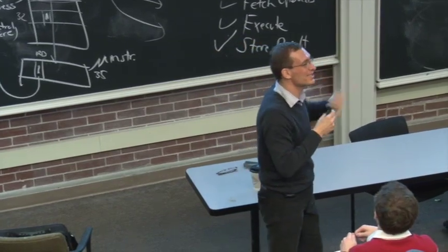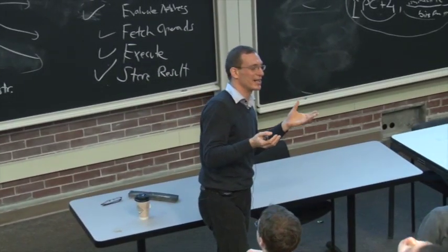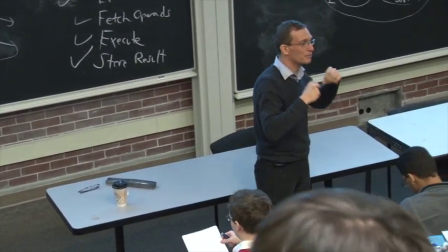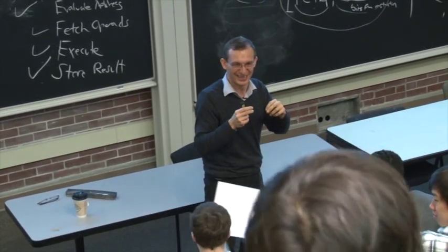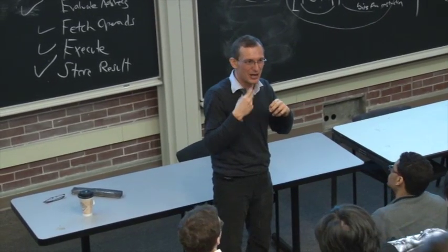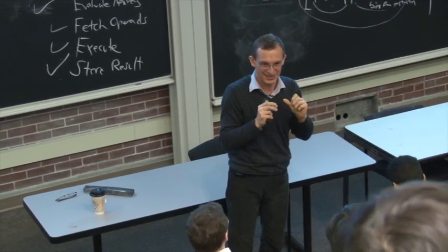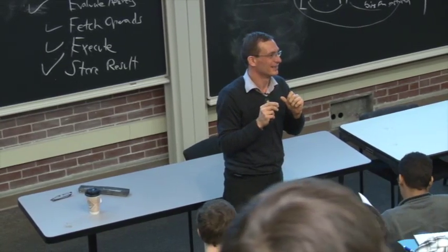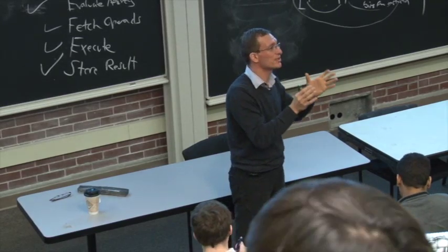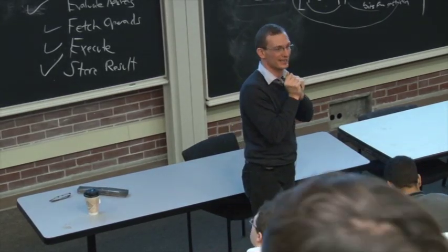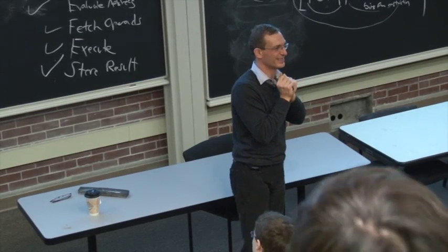A Mealy machine, basically, is a machine where the output is generated on the transition. So output is not only dependent on the state, basically. Whereas a Moore machine is one where the output is a strict function of the state only.